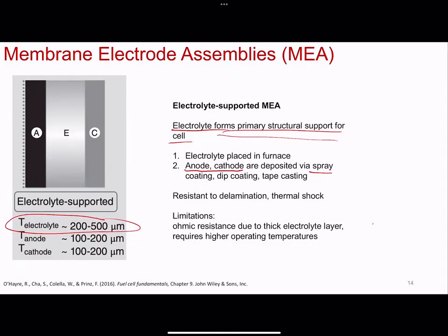So while you avoid, let's say, higher costs of solvent, vats and vats of solvent, drying off the solvent, and recycling the solvent, you're limited by size, and you have to now evacuate the system. The time that you have to wait for the chamber to pump down could be a problem, but you do get more uniform films, which is why the photovoltaic community sometimes sputters, because that's what they need.